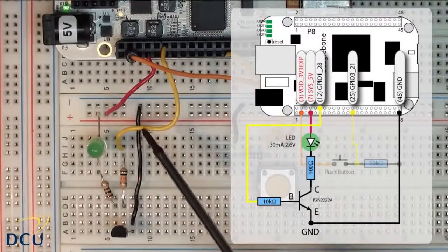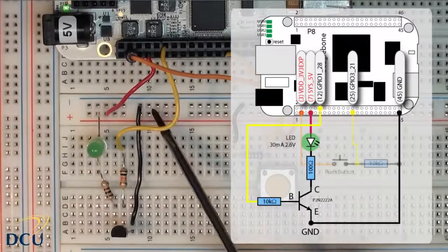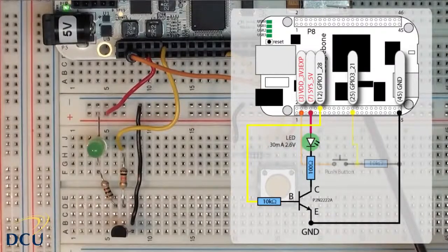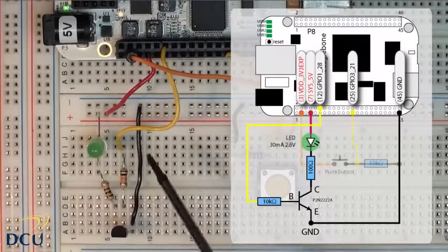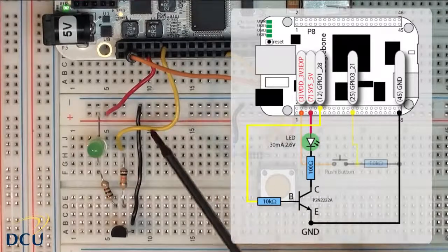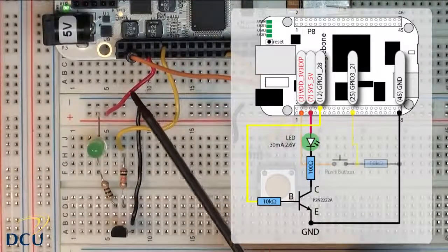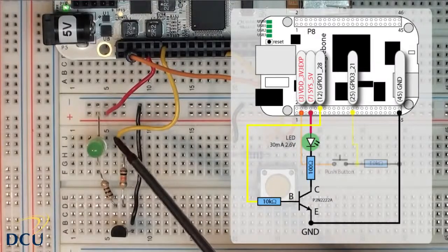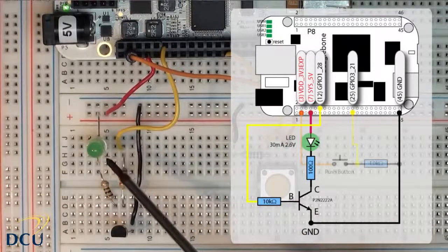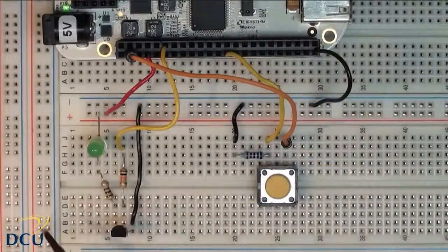That's the marking that's down for that. Finally the emitter of the transistor is connected via the black wire to ground, and this is my ground rail, which is connected to pin 45 of the Beaglebone, which is a general ground. So that's the wiring of this circuit. This circuit ensures that when a very small current is received from pin 12 of my Beaglebone, this triggers the transistor to turn on, in which case we have a current that flows from the collector to the emitter of the transistor, lighting up the LED using this 100 ohm resistor to drive the current through the LED. So that's the circuit for the output side.